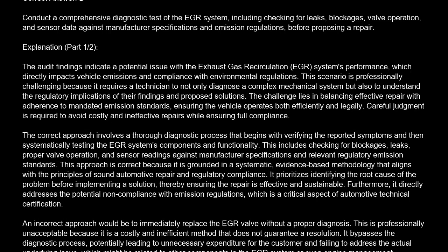Correct answer is D. Conduct a comprehensive diagnostic test of the EGR system, including checking for leaks, blockages, valve operation, and sensor data against manufacturer specifications and emission regulations before proposing a repair. Explanation. The audit findings indicate a potential issue with the exhaust gas recirculation (EGR) system's performance, which directly impacts vehicle emissions and compliance with environmental regulations.